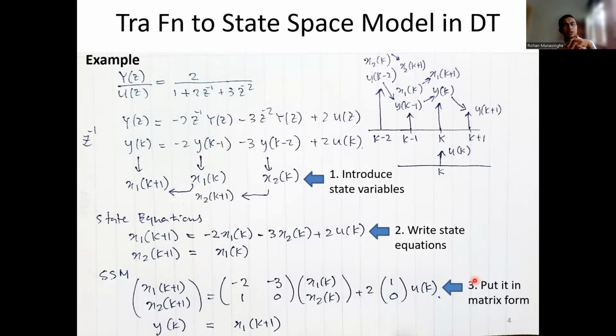I can tell you a story in continuous time. If you have, say, a 10th order differential equation in your plant, you write down the equation and you get a 10th order ordinary differential equation. That is your model. It's tough to deal with a 10th order differential equation, right? So what we do is we break it down into 10 first order equations. Even though you have 10 equations versus one equation earlier, these 10 equations are all first order, so it's very easy to implement and solve first order differential equations. So even though we have 10, we don't mind.